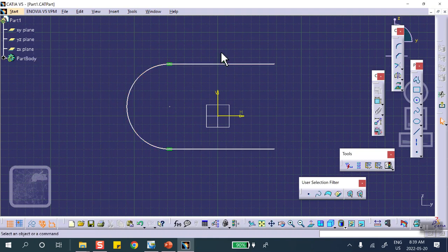Except that it's not. I want to make sure it's symmetric. Just to feel better, that's all. Not in this problem, though. There is no planar symmetry in this problem, and we'll talk about that in a minute, why there are no planes of symmetry. Because the top is clamped, the bottom you do something else to it. The shape is symmetric, but the top right corner is clamped, and the bottom is not. If I was applying that force on both sides to move this thing by 0.01 up, 0.01 down, yes, this is a plane of symmetry, and we're going to worry about it, but not in the present model.